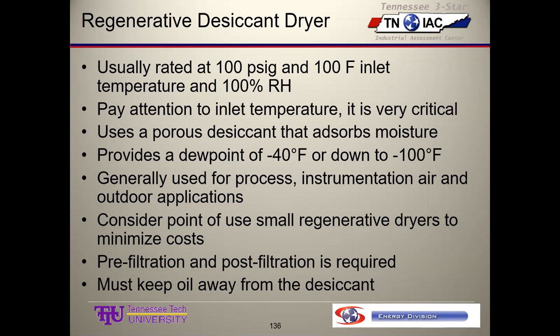So these people had refrigerated air dryers, which get you a dew point of 36 to 38. And then they had desiccant air dryers that can go anywhere from -20 to -100 or -120. So they were drying it and then drying it again. Me and this buddy of mine, Greg Harrell, were in there. And we said, we don't really think these refrigerated dryers are doing you much good. Your desiccant dryers have more than enough capacity. You could save $35,000, $50,000 a year by turning off the refrigerated dryers because it's a little refrigeration system with a compressor and all that.